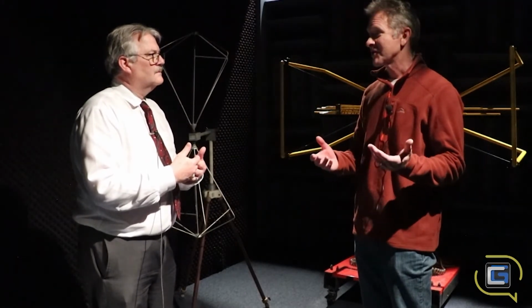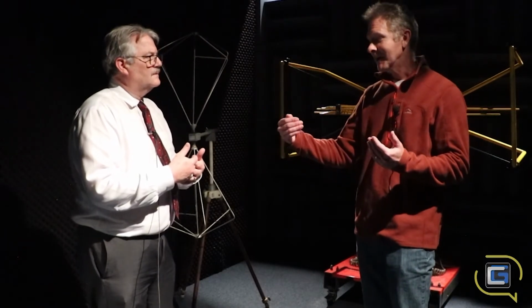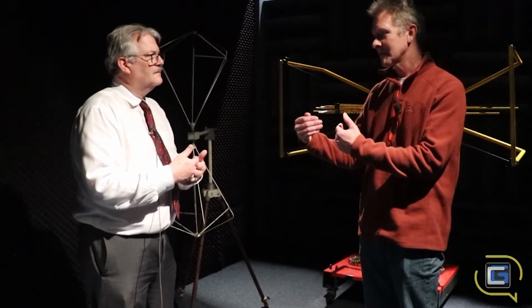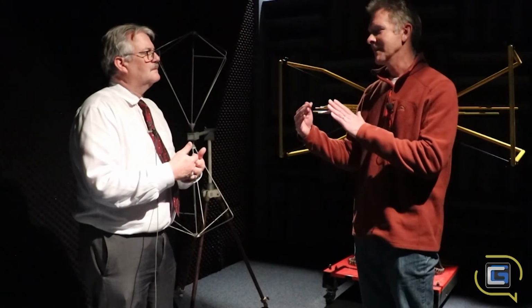In order to get lower frequency cutoff, you need to go with larger size components. What happens if you have the noise coming out of the unit, and it's being filtered by a small filter and then trying to be filtered by a large filter, you can end up with the filters fighting against each other, and they actually create peaks that are worse than if you didn't put that big filter out there.